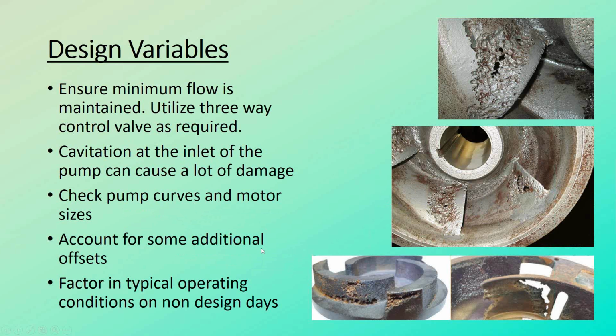And then you want to size your pump for a design day, but when you're looking at the efficiency of it, you may look at having the peak efficiency at more of a 70% area where your pump's normally going to be operating. It's not always the design day. The majority of the runtime of the pump is not going to be on a design day. And so making sure that the pump is efficient on a non-design day is very important.